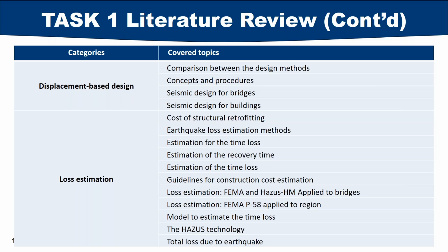So we are trying to find this connection, how people emerged from force-based design to displacement-based design, and how displacement-based design emerged to resilient-based design or performance-based design first. Again, we focus mostly on seismic because many of these design frameworks were developed only for seismic, but then later on they started being used for other hazards.